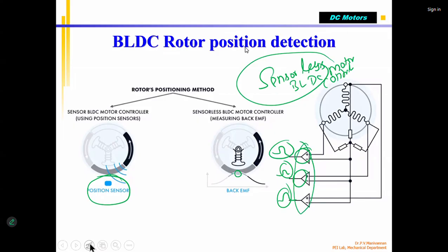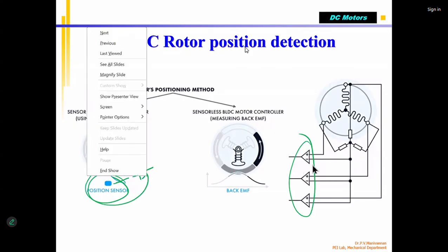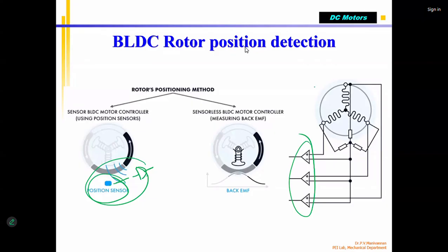The main problem here is that you are going to use an op-amp circuit. This also increases cost. But we have to see whether a Hall effect sensor also needs an amplifier. A Hall effect sensor also needs an op-amp. Just using the op-amp comparator, you can detect the back EMF position. So you compare whether the sensor with the amplifier is costly or this is better. Generally, back EMF based control will be simpler because you save the Hall effect sensors.